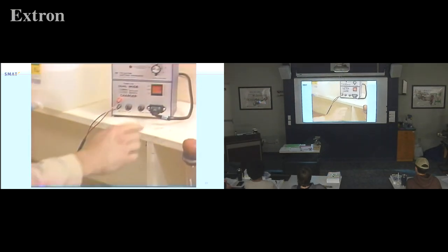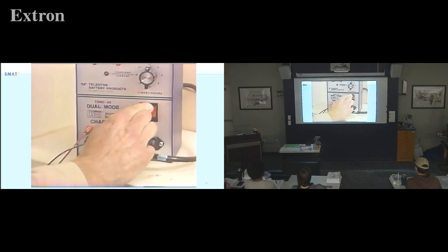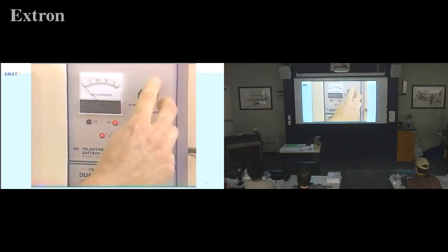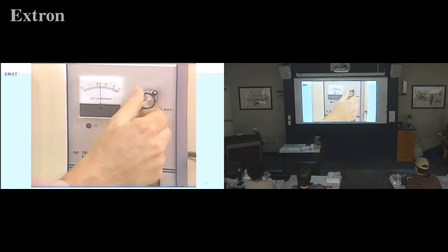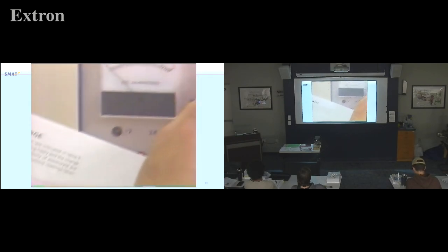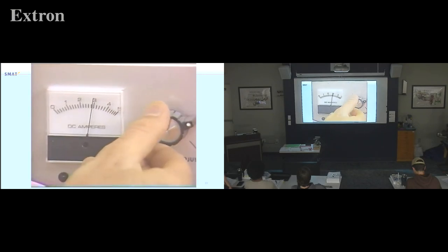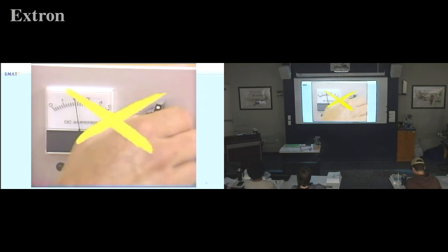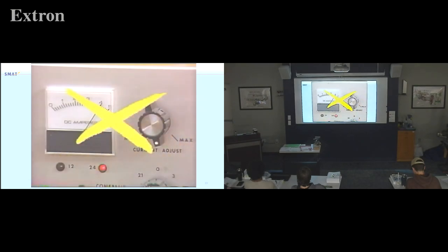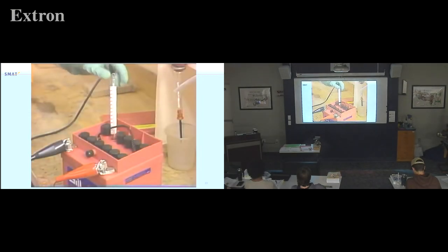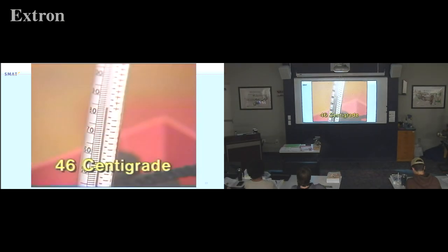If possible, charge the battery using a constant current charger, which does a faster, more efficient job than a constant voltage charger. Teledyne can supply this type of charger. Be sure that you adjust the charge rate to that specified in the instructions packed with the new battery or in the Gill service manual. Never attempt to speed the charging by using a higher than specified current. This could permanently damage the battery. While charging, keep cell temperatures below 115 degrees Fahrenheit.